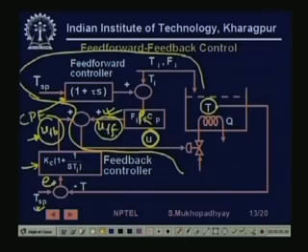So you will get a lot of speed, in the sense that most of the input which comes from feed forward will come quickly. Only a little input will not come because of the model inaccuracies, and that little input will be provided by the feedback. So even if that little input comes slowly, much of the correction will come very fast. So you will get a very good response and also in the steady state you will get no error because of the feedback corrections. So you got the best of both worlds.